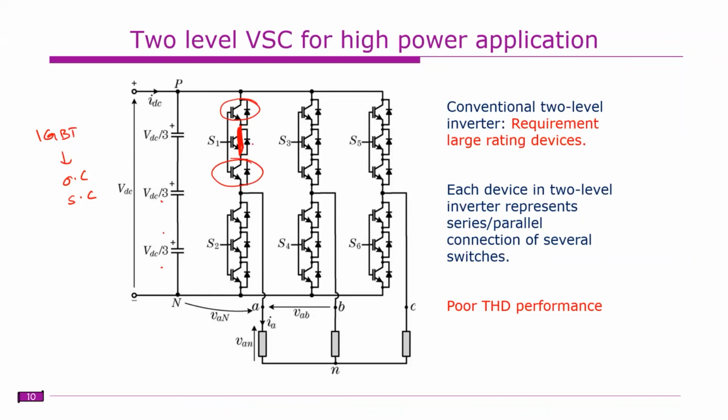So which is better? Reliability is one of the important aspects when you have power electronic devices: how reliable is your product? Is open circuit better or short circuit better? Short circuit. So short circuit is better, which means you can still use it. We have some factor of safety, so if one device has failed, you can still use it.